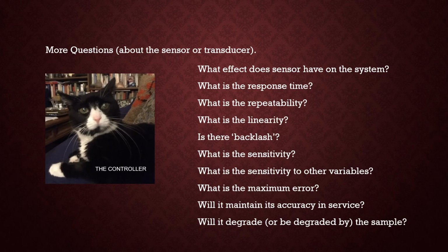My little friend has many questions, this time about the sensors and transducers. These are the types of questions you ask when you create or devise a new circuit or a new device to make the measurements. Namely, does the sensor have an effect on the system? What's the response time, repeatability, linearity? Linearity is nice because it allows you to create calibration curves based on simple linear forms.